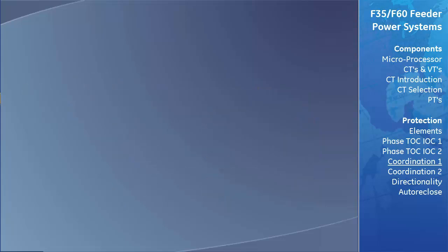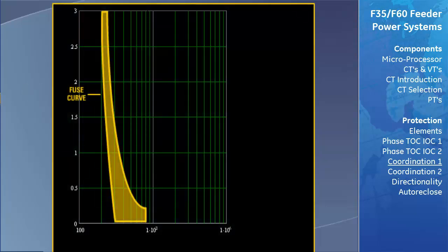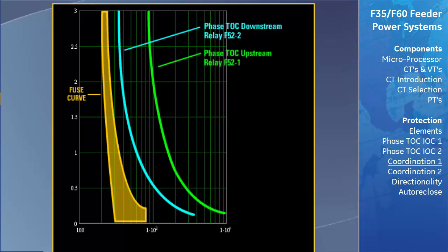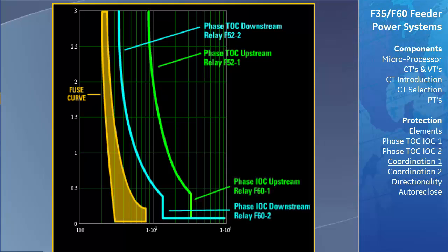The setting of a series of time overcurrent elements on a feeder or distribution circuit begins at the point farthest from the generating source. As the elements are set and coordinated back toward the generating sources, the time required to clear a fault becomes longer as the source is approached. Under certain fault conditions, this could be a disadvantage, and so instantaneous overcurrent elements are used in conjunction with the time overcurrent elements to provide high-speed primary protection. These elements must be set to pick up under maximum fault current conditions for three-phase faults somewhat short of the end of the line. The shaded area of the figure illustrates the improvement in tripping time obtained with instantaneous elements.